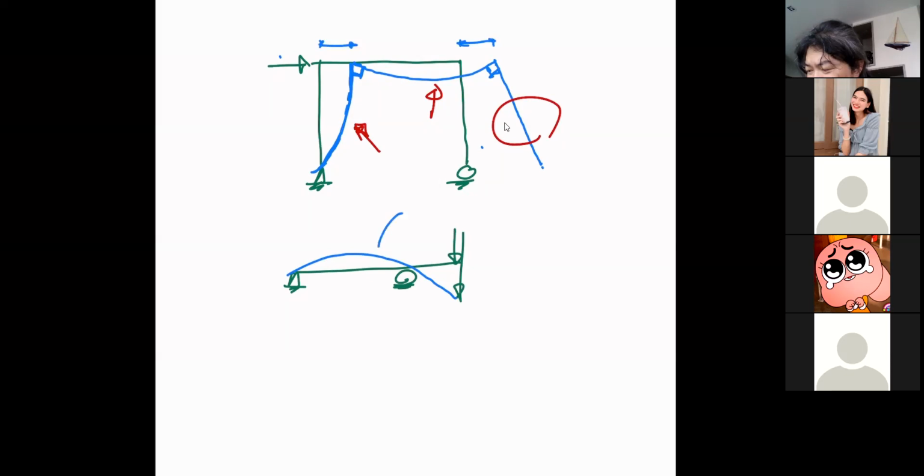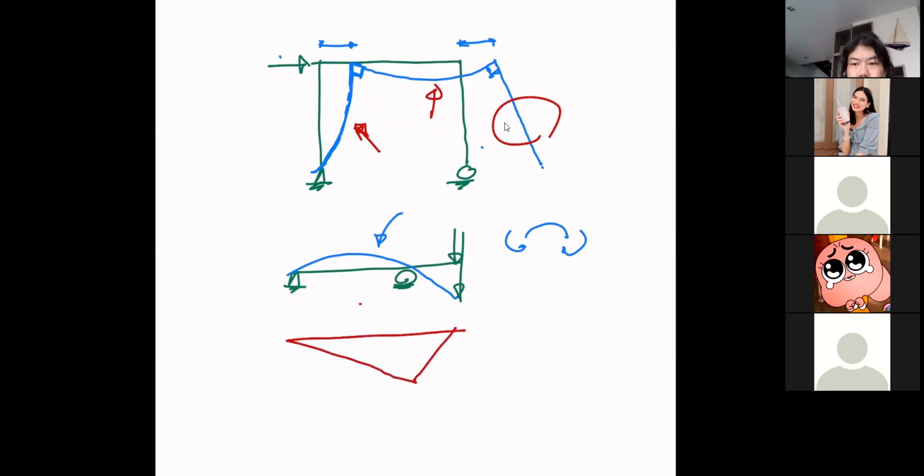And what kind of curve is this? This is a negative curvature, right? So when you see this, you should know right away that your bending moment diagram is going to look like this, simply because your beam will have to deflect that way. So one day, if you practice enough, if you accumulate your experience enough, you will just see it right away.